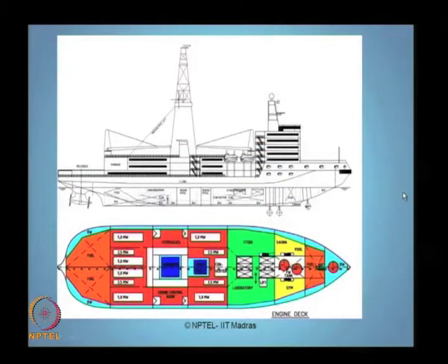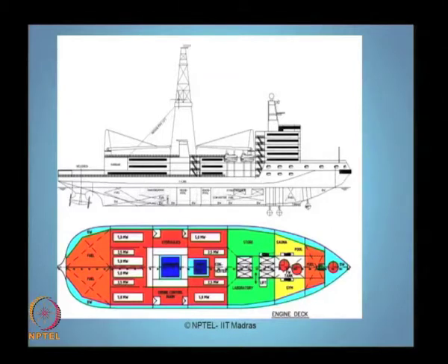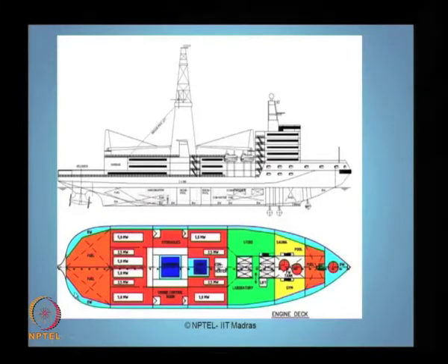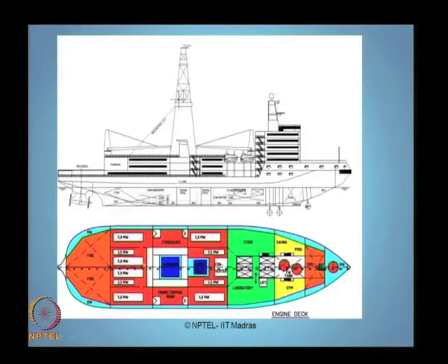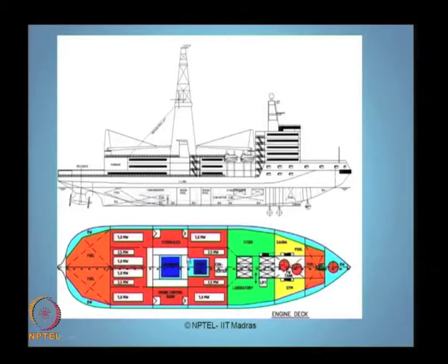The plan and elevation view of a drill ship, naval architects can easily understand and appreciate the necessity of this plan. You can see this is basically the plan of a ship which is conventional, but I am here making alterations to put a derrick over this. So, the essential alteration is a very big moon pool at the center and one more moon pool on the side.